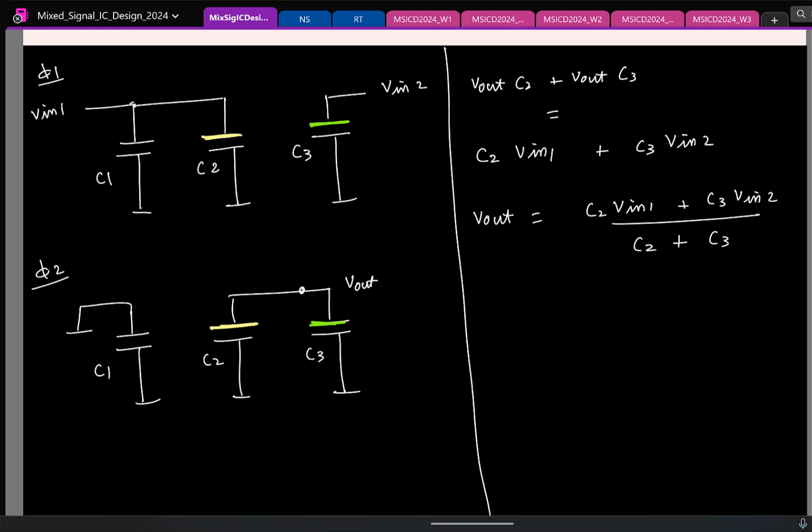So till now we have seen switched capacitor circuits that basically do this. We have sampled some signal V of n. We have applied charge conservation on only the C2 part. Don't look at plates, look at a particular node, right? It's basically KCL. We are choosing a node, looking at the delta Q flowing in both sides to be 0. Delta Q is basically the current charge minus the previous charge. So you look at the charge in this, the charge in this. Clear?